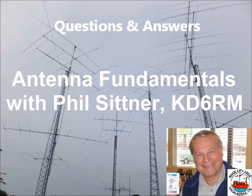And over here there's a little tiny resistor. Those are the 3 elements that make up the characteristics of an antenna. We're modeling this. We're pretending that it's an antenna. And on the screen, it looks exactly like a real antenna would. I don't think anybody disputed there's that SWR curve. And again, I showed you how the Smith chart tells you whether the antenna is too long or too short for the frequency you're interested in.